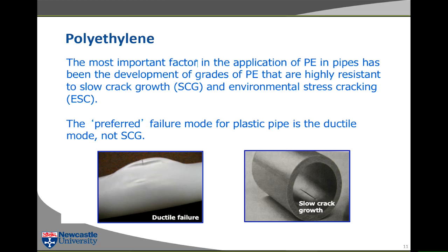But what happens, in this region I said, where you stretch the material, it lines all the molecules up and makes it much stronger. It makes it stronger in the circumferential direction. So this stuff is actually stronger. In fact, they actually strengthen some pipes by stretching them, by expanding them. We'll kind of go into that.